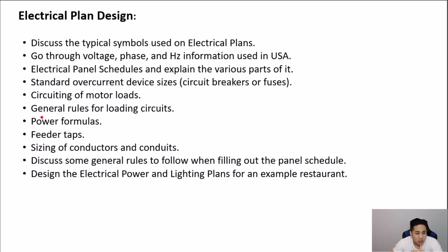Then we'll talk about general rules for loading circuits. There's a certain percentage that you have to load a circuit to, because if you load it too much, there's a potential that it can trip the breaker or the fuse. And if you load it too much, you might not have any room for future expansion onto that circuit for additional loads.